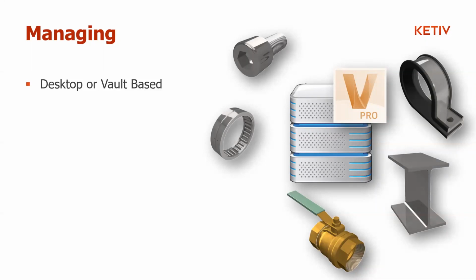Now, there are ways to share the desktop content with other users by putting it on a shared folder, copying the libraries and sharing them with everybody, and you'll be able to create your own custom content center library. But anybody will be able to browse out to that folder and make changes, maybe some unwanted changes. It's less secure. If it's vault-based, it's much better. You have to have very special permissions to be able to edit those files.